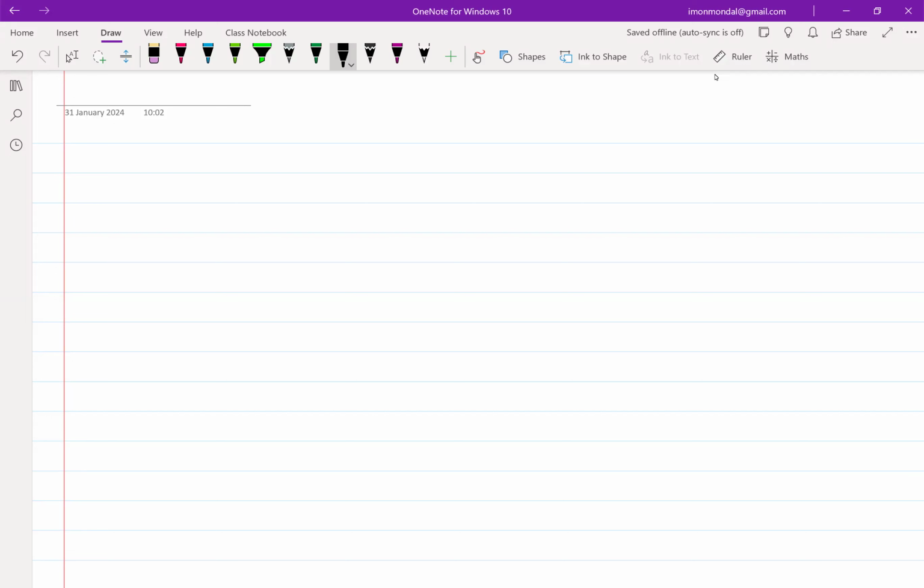In that case, I can replace that nonlinear element with a resistor of value 1 over del I del V, where del I del V is evaluated around the operating point. By doing that, we found that if we have a diode, you can replace a forward biased diode with VT over ID, where VT is the thermal voltage and ID is the quiescent current. But if you have a generic nonlinear element with some function f of V, then I can replace that element with 1 over del F del V, right?